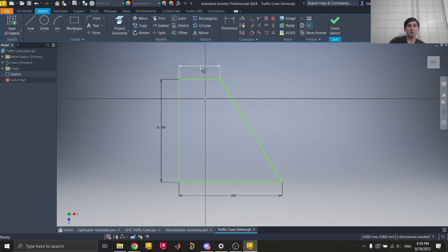I'm now going to do the same thing here, but I don't have to just type in D0. I don't want to have to go and look up every single dimension because, as some of these parts get a lot more complex, you're going to have a lot of things. And it's like, oh, did I use D147? Oh, no. One way that you can do it that's a lot easier, similar to Excel, how you can just click a certain cell to reference it, you can just click a dimension instead.